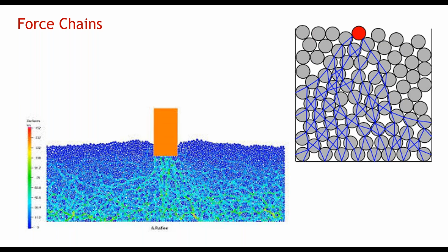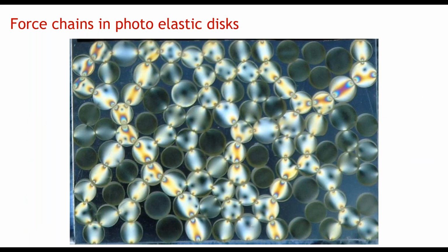It's possible to view force chains in a model using photoelastic disks that change color under stress. The chains of force are clearly seen in this model using the photoelastic discs. Forces are transferred by particle-to-particle contact. Compaction brings about a degree of stabilization by causing this to happen. It reduces the potential for particles to move and rotate, which stiffens and strengthens the granular layer.